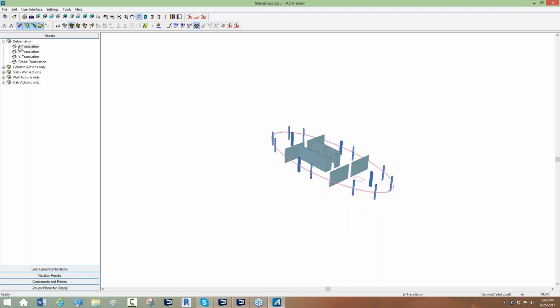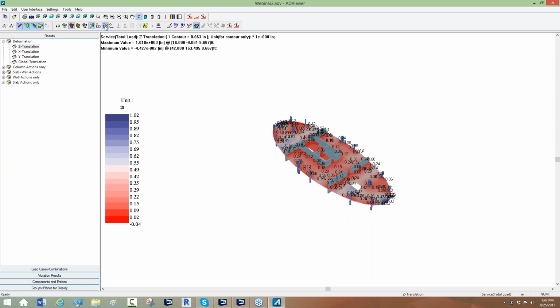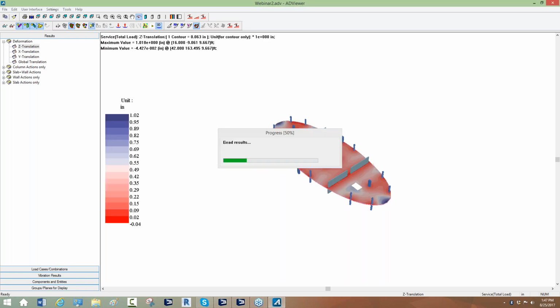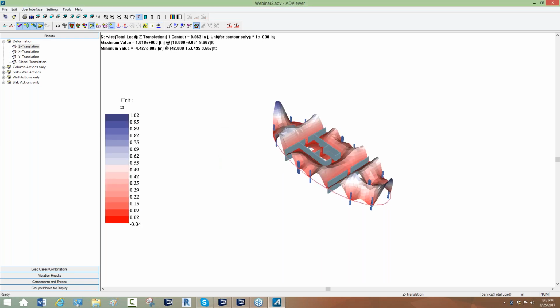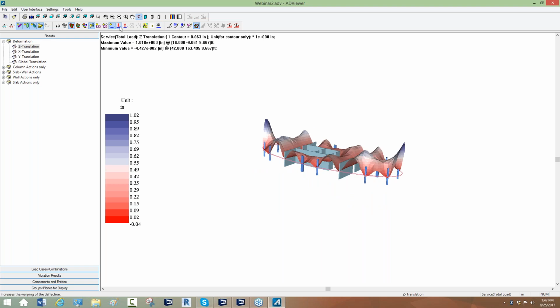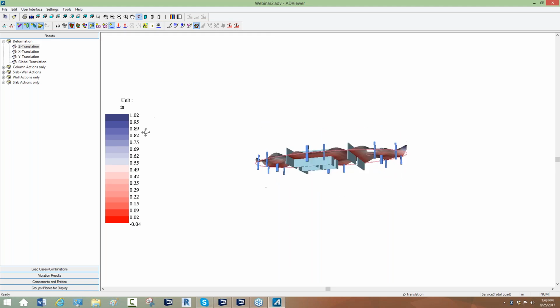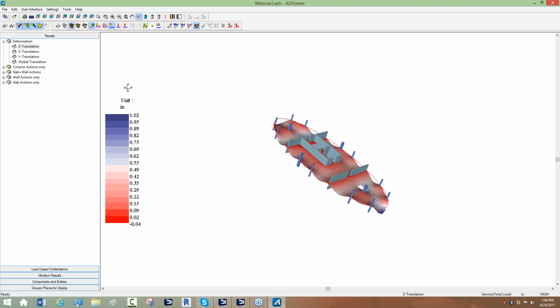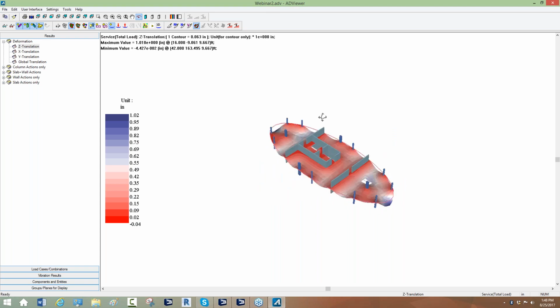So if you go here, for example, select the result, Z deflection, turn the result on, the program will show you the results here, and you can warp this easily. You can deform or warp the actual color contours in this view. So this view is still used. We're actually phasing this out in the next year or two once everything is built in that result display settings, but it's still a useful tool. This is flipped upside down. It should look like this.